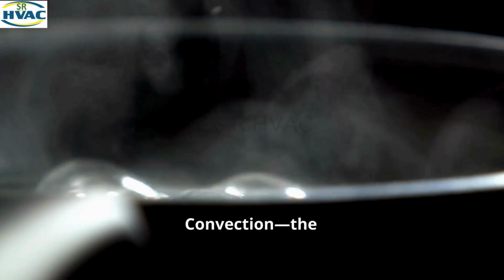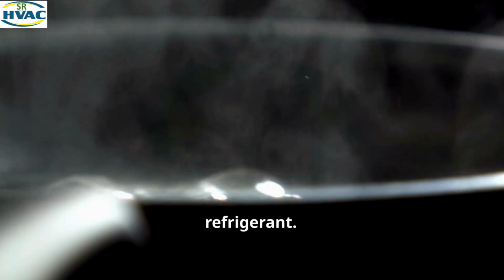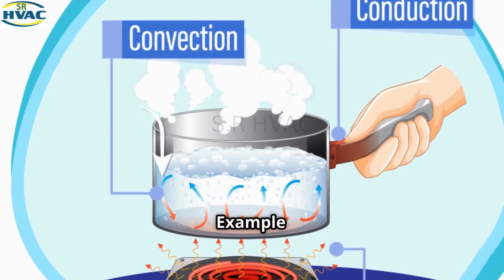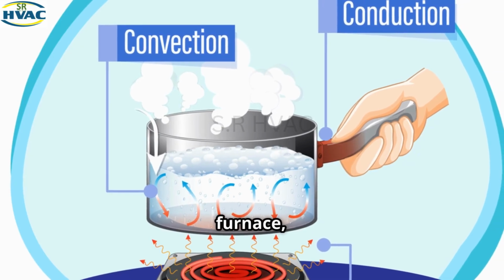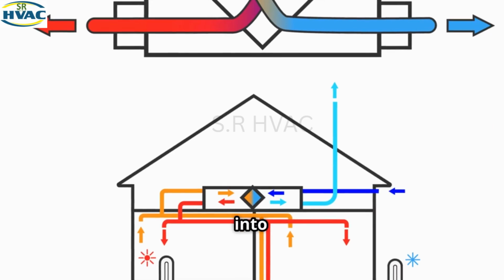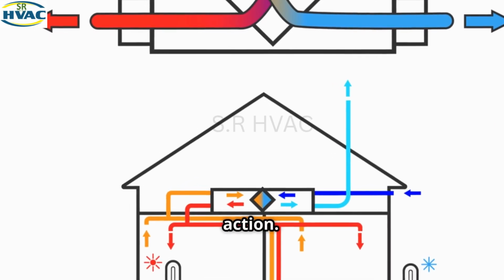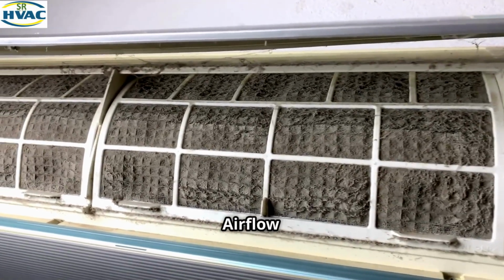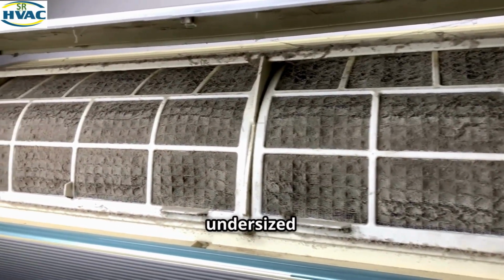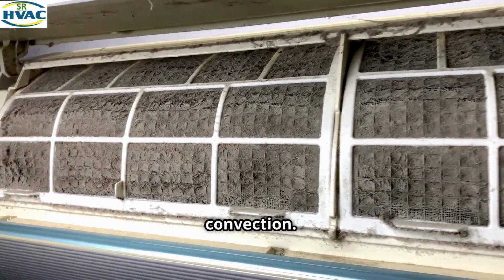Convection. Next is convection, the transfer of heat through fluids or gases like air or refrigerant. It happens due to movement. Warm fluids rise, cool fluids sink. Example in HVAC. In a forced air furnace, the heat exchanger warms the air and then a blower pushes that warm air into the duct system. That's convection in action. Why it's critical? Airflow issues, that's often a convection problem. Blocked vents, dirty filters, or undersized ductwork can all restrict convection.